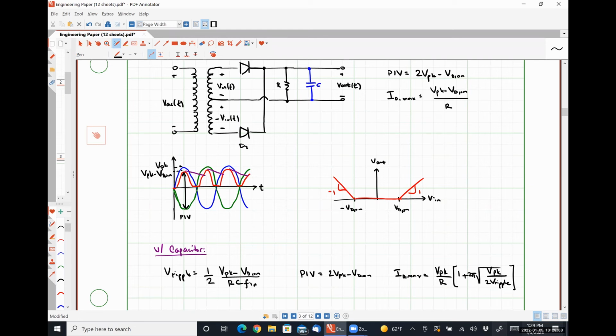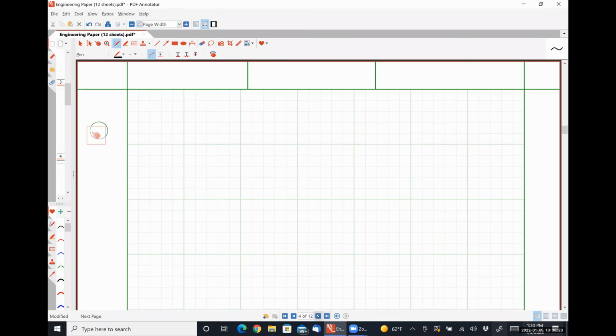The principal drawback of this full wave rectifier is that it uses a center tap transformer, which is a reasonably expensive component. Okay. So we can get effectively the same output by utilizing what's called a diode bridge, where a diode bridge just uses a standard non-center tapped transformer. So our bridge rectifier is going to look something like this.